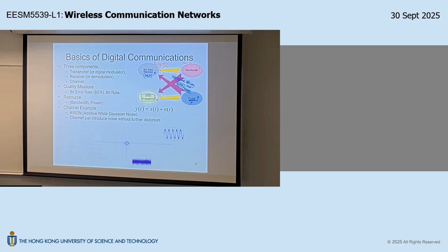Is that okay? So this modulation family, so-called MPSK, this is called high spectral efficiency modulation. The way you use that is you want to increase the bit rate without increasing bandwidth. So that's the high spectral efficiency. Spectral efficiency means bit rate normalized with bandwidth. This is called spectral efficiency. So when you engage in this MPSK for large M, you basically increase this log 2M term, increase the number of passengers per minibus.